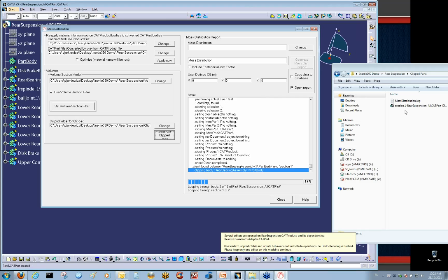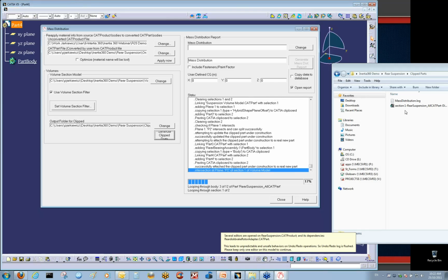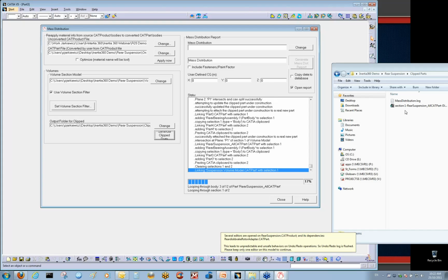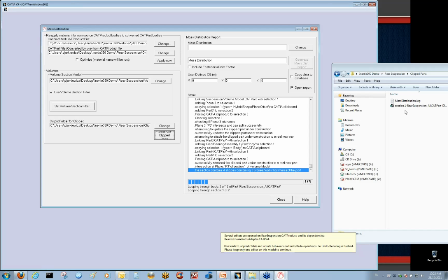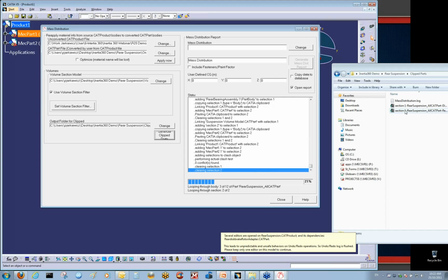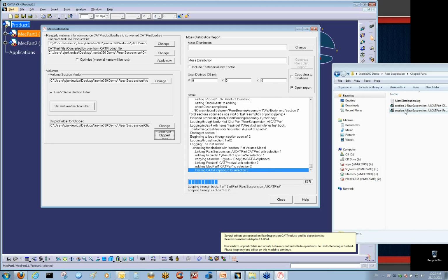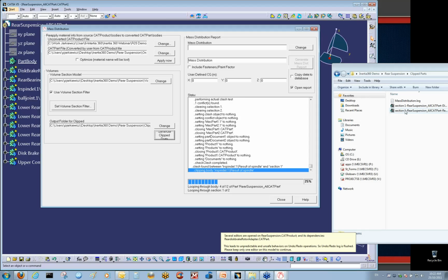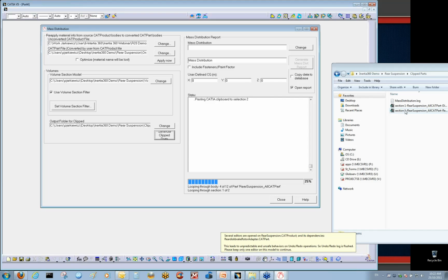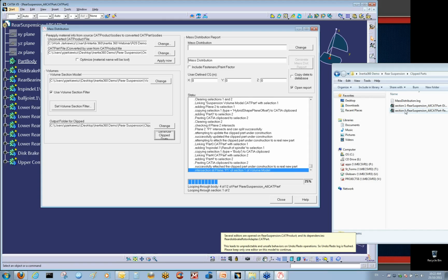You were shown an example of that or a sample of that in my PowerPoint presentation, how it gives you volume 54, volume 55, for example, and it shows you all the parts that cross into those particular volumes. And then it gives you the mass properties, the total weight of each one of those parts, moment of inertia, center of gravity of the overall volume, and each individual part.